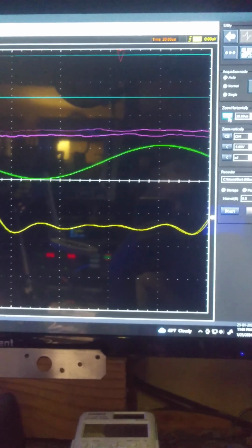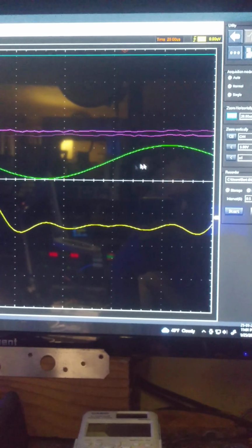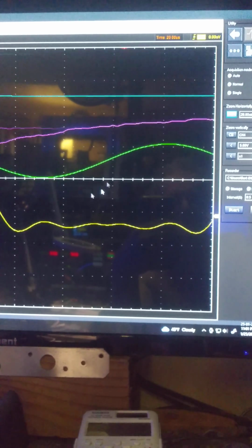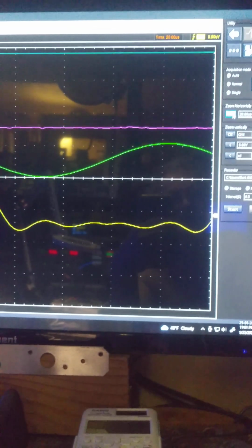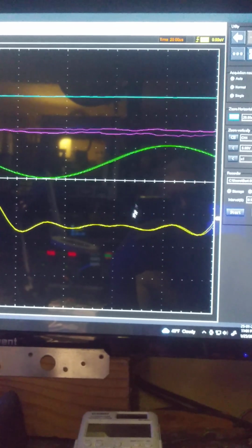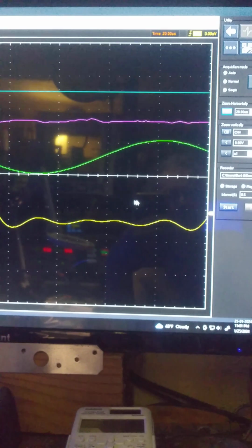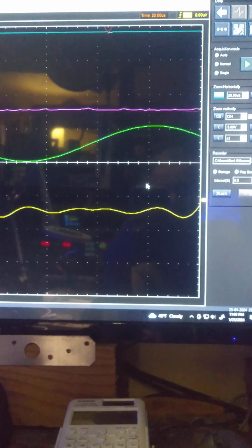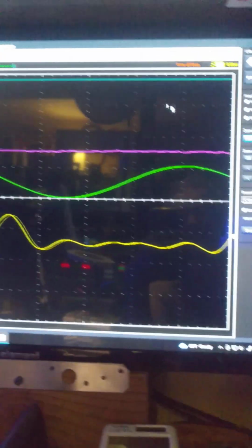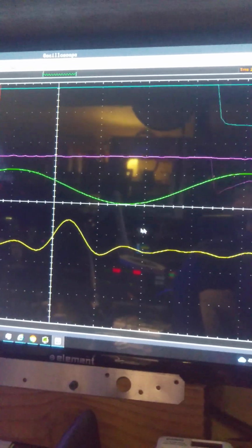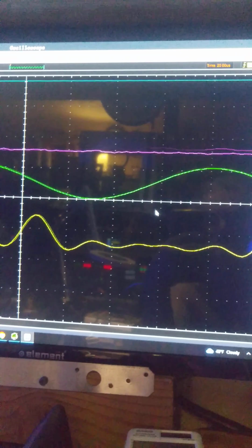But because of the aliasing problem, if there are signals outside of that range, you're going to have to really sample a lot. If it's, let's say, a 2 hertz signal, you'll probably want to sample it like 100 times that, just to make sure. So that's a lot more data you're going to generate, and I'm still not sure if this is capable of recording that much data or not. It should. It's on a PC.